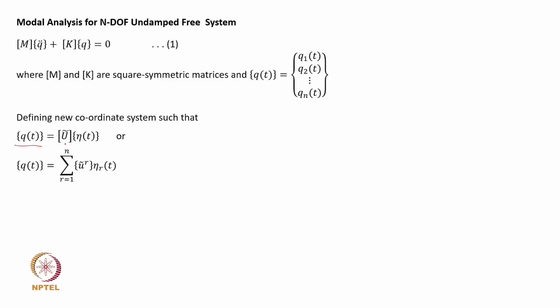That is done by expressing the physical response as a summation of the response in the principal coordinates, and this has already been shown, extrapolating what we learned for a 2 degree of freedom system. This expression can also be rewritten as a summation series, and we have also discussed how this is true. So, it is basically a summation of contributions from all the principal coordinates, and the contributing factors are your mass normalized modal vectors. Their summation series will give you the total physical response.